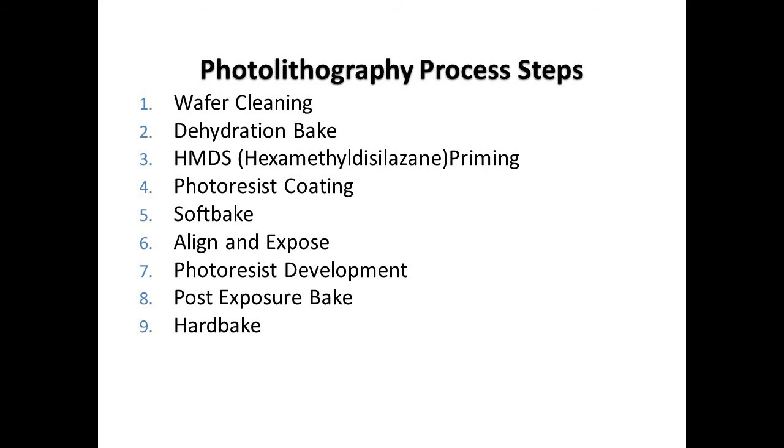After you have exposed it, there's also a relation between how long you are going to expose and how strong your UV is, with the photoresist. If you use a thick photoresist, it may need more time for exposure. It can take like 1 minute. But for a thin photoresist, maybe 5 seconds or 10 seconds will be enough, or even 2 or 3 seconds, depending on the application.